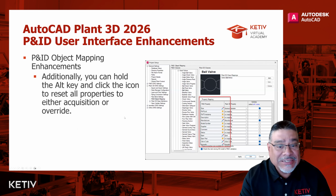Also building on this, additionally, you can hold your Alt key and click the icon to reset all properties either to acquisition or override as well. So right now, as you know, these little icons here that have the little lightning bolt symbol are the ones that you're acquiring the information for. The other ones here with the pencils are the ones that you've overwritten something already. So if you wanted to switch these or reset them, that's how you would go through the process with those items.